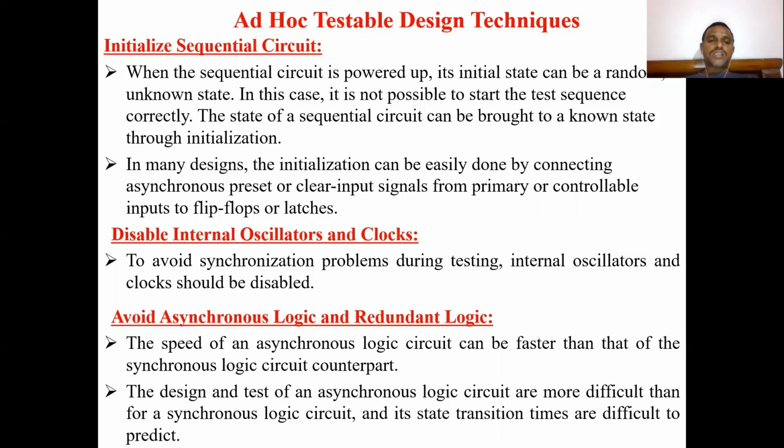The next one is to disable internal oscillators and clocks. When you are going to test a circuit, we have to disable the internal oscillators and clocks, because they generate frequency signals or clock signals. If you enable them, the input test vectors we are applying cannot be applied properly.